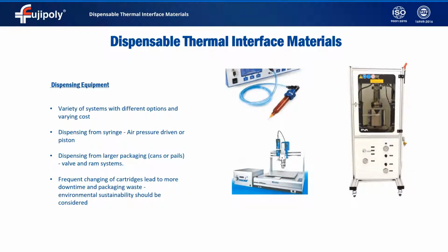Dispensing equipment ranges anywhere from a simple controller with a compressed air line to a tabletop system or a large pass-through robotic dispensing cell for use on a production line. The smaller systems are pneumatically driven and controlled by time and pressure. These are ideal for lab environments or for small production runs. Obviously, there's a big jump from just having a simple controller hooked up to an airline to having a tabletop unit where, potentially, given the surface area, an operator could place more than one device, run the program, and step away for some time.